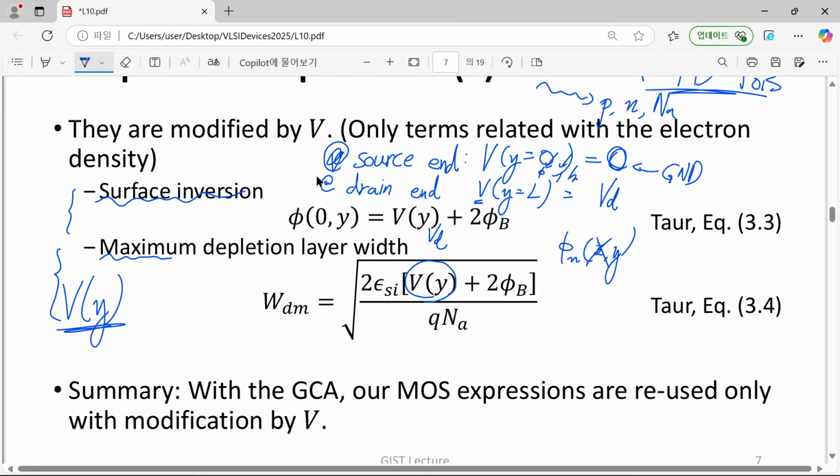Although it is just a theoretical artifact, it is exact. We can define surface inversion in this system, but maximum depletion width is not actually defined. We can even have a wider depletion width because surface potential can be slightly increased beyond the onset of strong inversion. But please treat it as just a rough estimation of maximum depletion width.